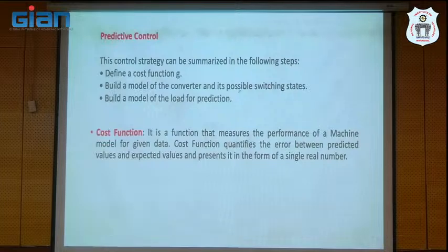See, in a PI controller, what are we doing? What is the input to the PI controller? Error. Here also we take the error of the control variables, the target variables. Torque error, speed error. If you want to control the speed, your PI controller will calculate how much torque we need to maintain. Then if you compare the reference torque with the actual torque, any torque error is sent through the PI controller, and the torque controller decides how much voltage we need to apply across the motor terminal.